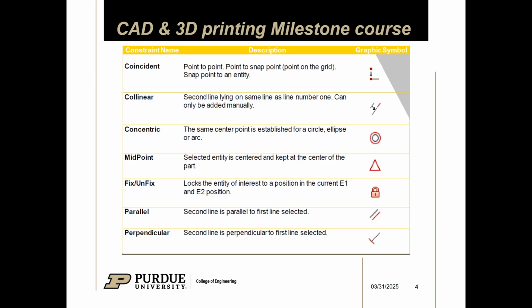And it allows you to focus on the certain things that you might want to be able to change later. So, for example, if you know this design might change in the future, but this thing you might have is always perpendicular, you can just set that to be perpendicular and then have some dimensional constraints elsewhere, in a place that you might want to be able to specify more. That might sound a little bit confusing, but you might start to understand it a little bit later. So yeah, there's a bunch of them up here.